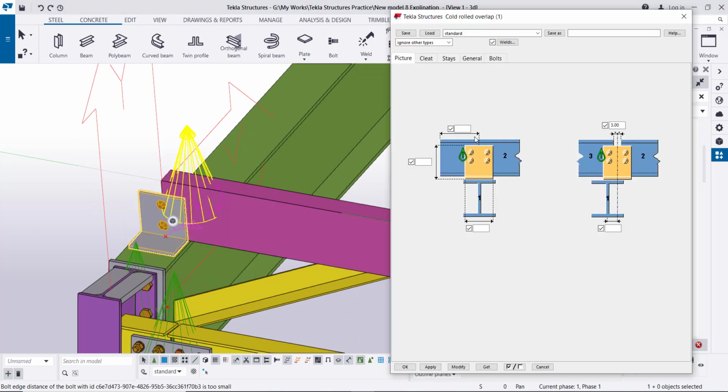Okay, here we have two cases. This is if the cleat or the connection at the end of the purlin, and here the connection at the overlap. Here we select 100 mm from center of the cleat, and here 3 mm equal, let us make it 1.5 mm, the gap from the center to one side of the purlins.